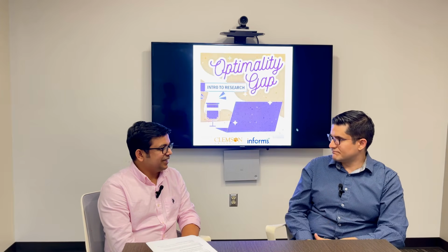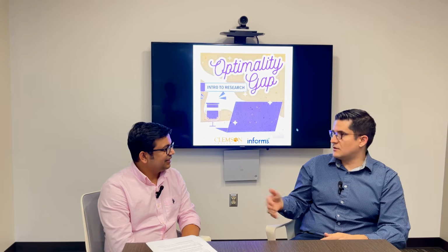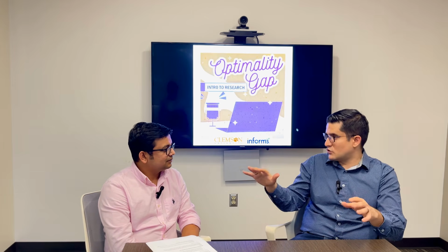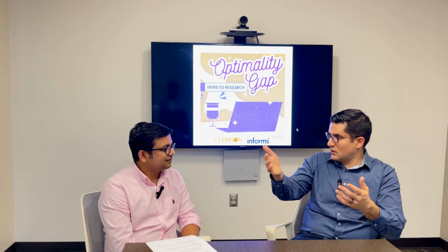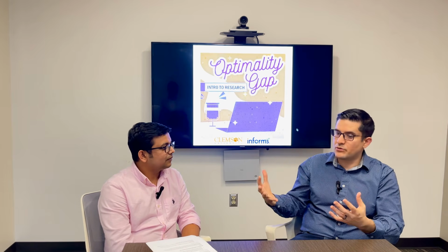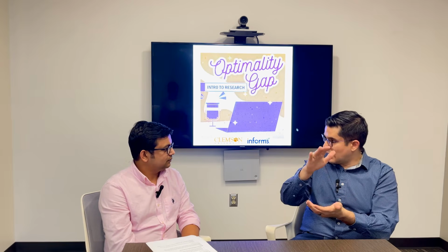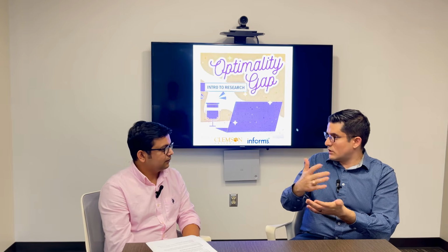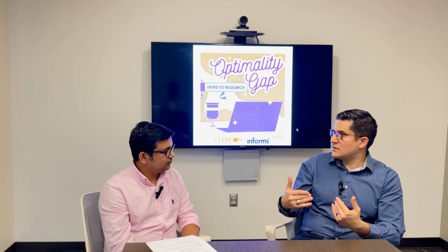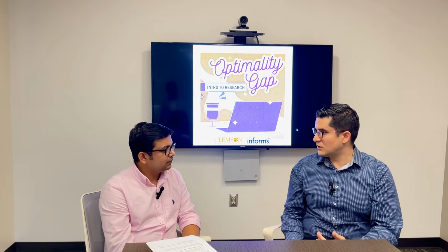I can remember from my electrical engineering class. Well, the wires that are out there to transmit electricity, they're rated for ambient temperature. So when there's heat out there, that will degrade the performance. So sometimes the system operator will, on purpose, load the transmission lines at a lower level, because they don't want to damage them. So implicitly, this degrades the ability of the power system to deliver electricity.